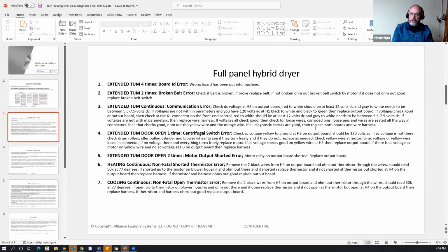It's very important. Just because you ohm out that yellow and orange wire and it ohms out good, again, we got to remember we're working with DC voltage, and with a crack in that wire, that DC voltage cannot jump that crack. When we're ohming, if the crack in the wire is touching enough, it will ohm through that. So it doesn't mean just because that orange and yellow wire ohms out good, that it's good, because again, that low pulsing DC voltage.